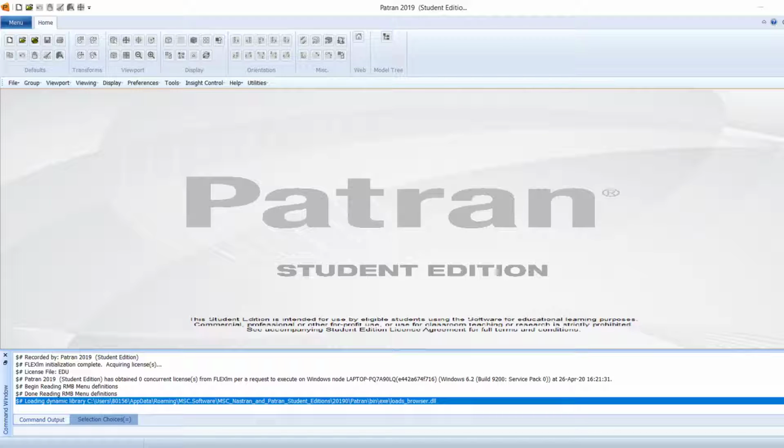Today we're going to do a Patran and Nastran tutorial where we're going to make a Parasolid solid example. The objectives of this example are to learn some of the steps you can use to create a B-rep solid, extrude a surface, make a shell, and edge blend, then create a finite element model, analyze the model, and post-process the results from the analysis. The software that we're using is Patran Standard Edition, as you can see.